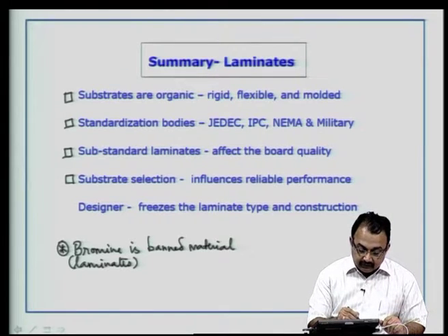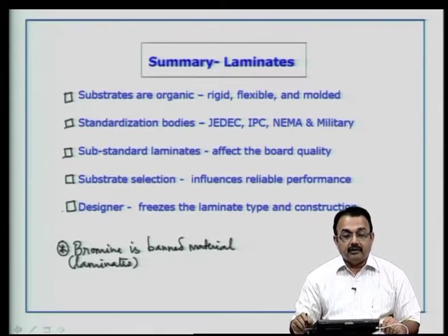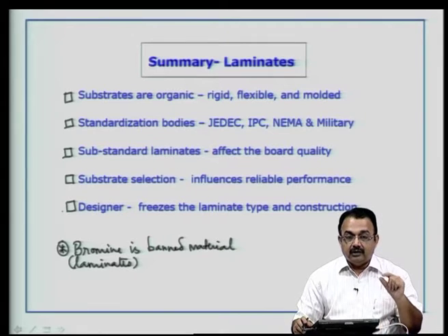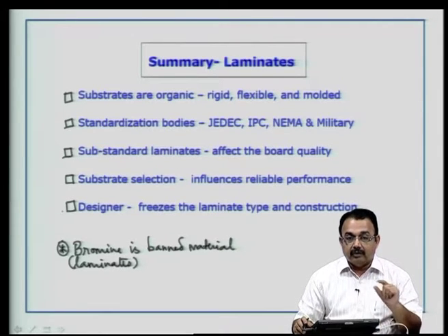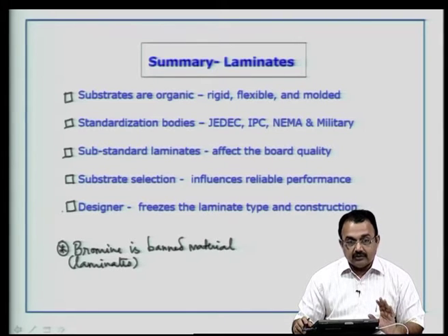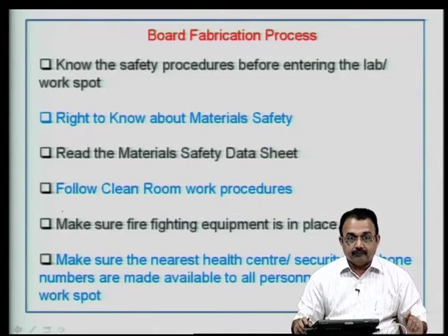So, designer, once again if I can remind you, freezes the laminate type. It is not the manufacturer who is going to take the FR4 or a polyimide or a Teflon. It is you, the designer, who has to decide what laminate you want for your electrical application or electronics application.